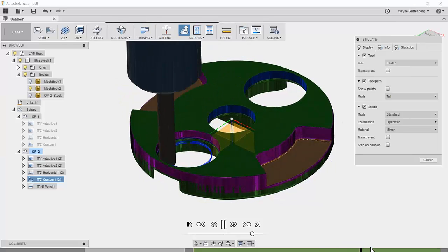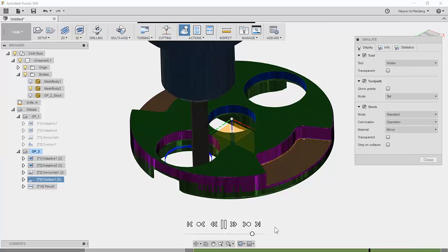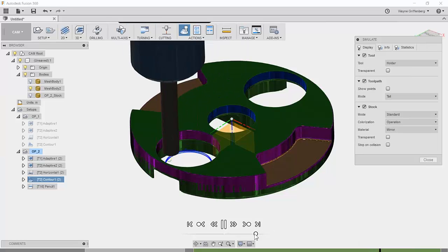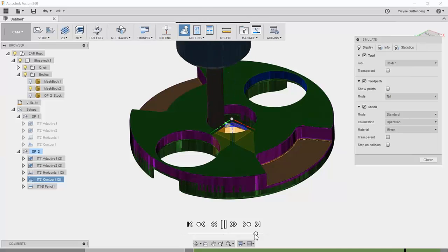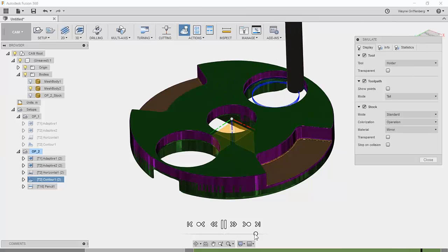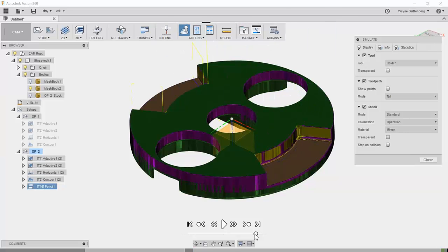So in cases like that, you're better off creating a simplified model of what you're going to machine and having the true geometry. I would agree with that. It's probably better, again, and also as Mike had said, the closer you can get to the true file or the real geometry that you're looking for, especially when you're doing things like soft jaws, because now you have one body dependent on another body, and that's really where you want to have solids to drive that.